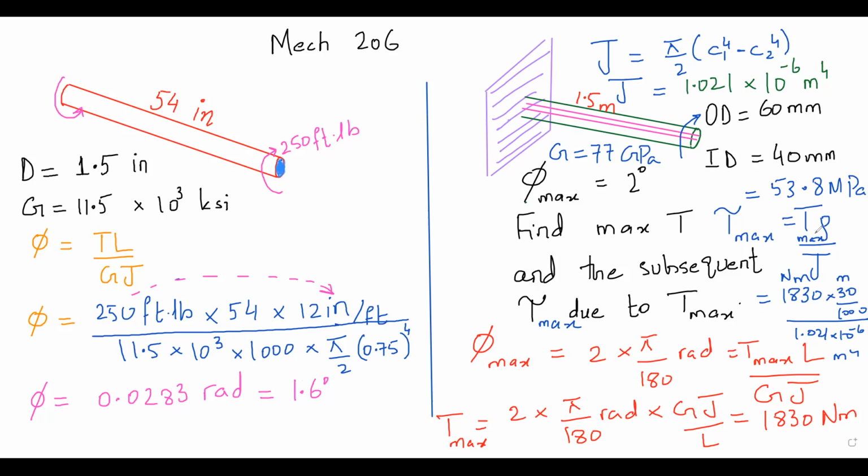The maximum shear stress that he gave me. Okay, everyone. Maximum shear stress here, TR over IP, it is 4.53 kilo-pounds per square inch. If you cannot find it, you can let me know. Okay, life is good.